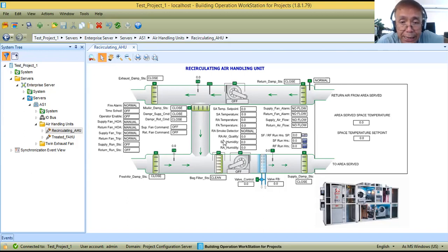Now, the first points are the start-stop for supply and return fan. So that will be 2 points provided in the motor control. What else? You have to ask for the monitoring points. So what are the monitoring points? Handoff auto status. This is the selector switch.